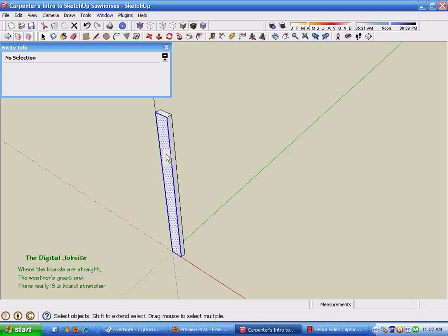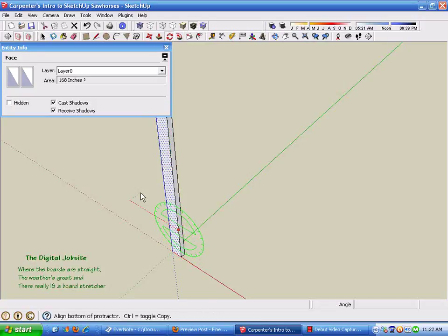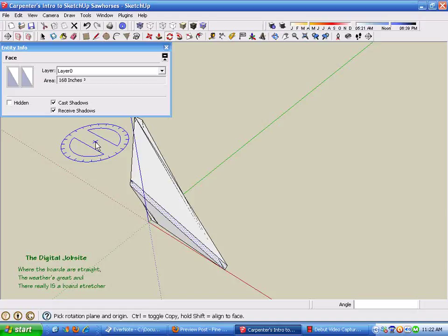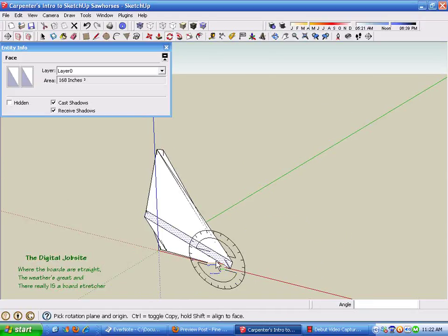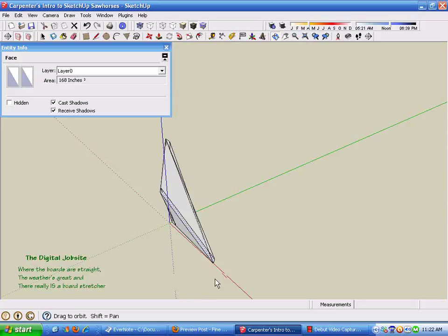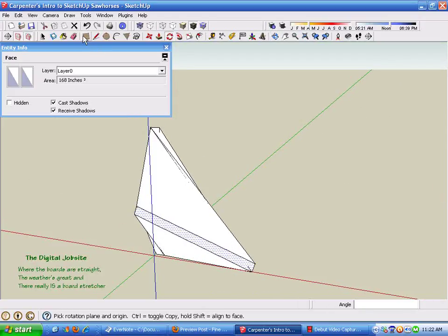And when I select anything, a line or a face or a surface, and then select a tool, it's going to operate on only what's selected. In this case, I had selected the face and rotated it, and it comes out with this ridiculous looking geometry here. That's what happens if you grab that face alone and turn it, which isn't what we want to do.